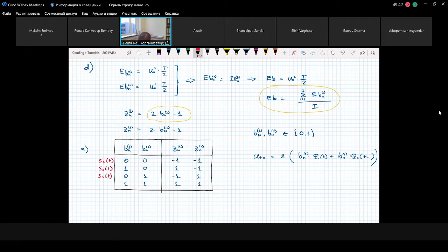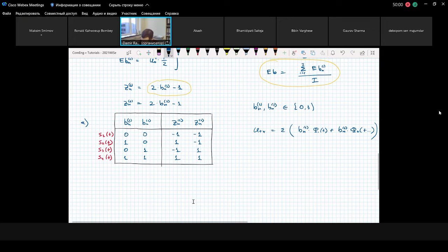So for each combination of bits, we say that it corresponds to a specific signal that we transmit. And you see what will be the intermediate quantities. I can write how each signal, starting from s1 to s4, will look in terms of pulse shape and then basis function. So I can write s1(t) as nothing else than -1 times phi1(t) plus -1 times phi2(t).